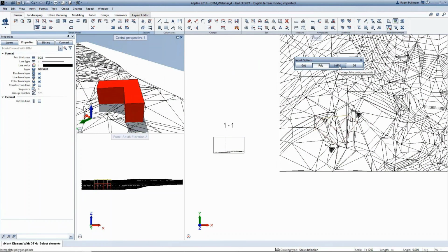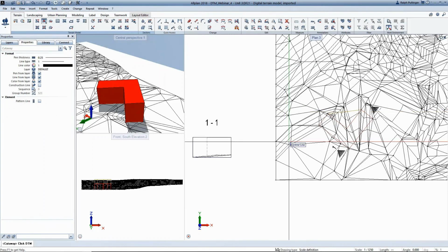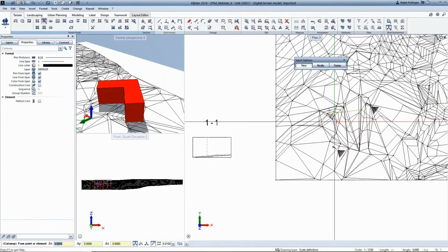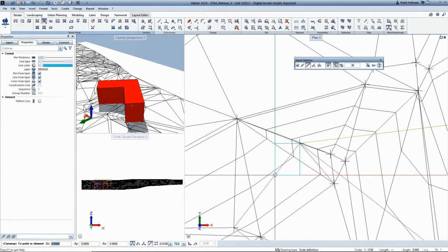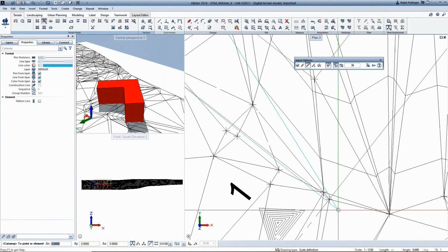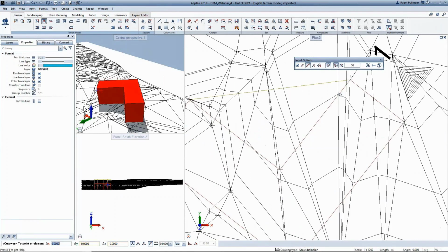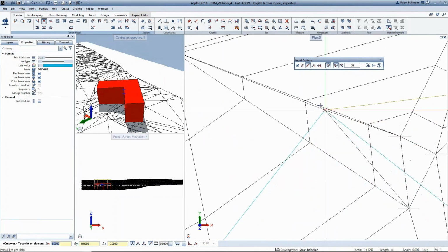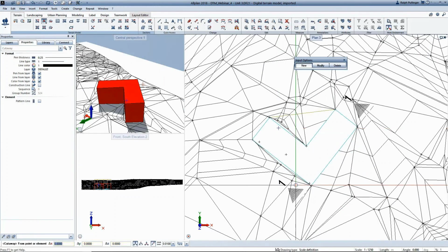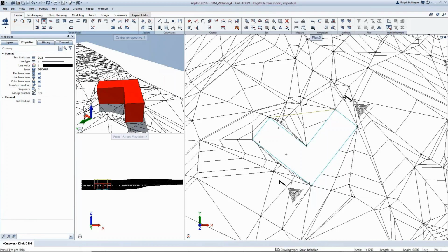If we have, for instance, a building, then we need to integrate that building with the digital terrain model. Once we have that integrated, Allplan will generate a series of interpolated points. Once we have those points, we can create what you can call an island, or a void cut. So we can cut a portion out of the digital terrain model to take in the building itself. We've just cut out from this model a whole load of soil based on the level at which we've placed that building. Hopefully that makes sense.